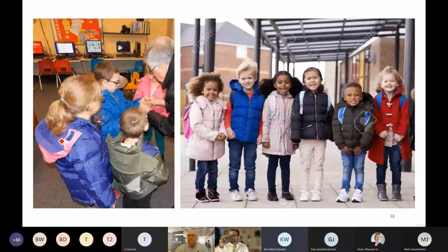So I wanted to jump in here for a second. Just looking at the relationship with particles versus the outdoor air, and how once the particles do get in there, because if the virus is in the space, how do we get them out? And you kind of touched on that. But there was one question about duration of time in the classrooms as it relates to air changes per hour and particles. So, for instance, if it's an 8-hour day and kids are changing classes in that space, in a high school environment, does that 8 hours, does that clock start ticking the minute the buses show up in the morning? Or is there a break in between? Say the space is unoccupied for 10 or 15 minutes. Where does that clock start ticking again?